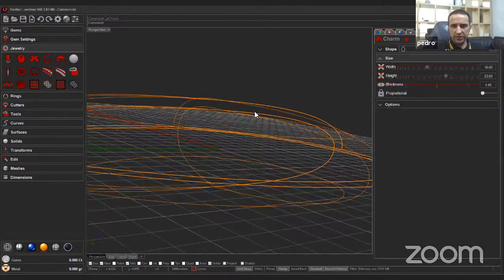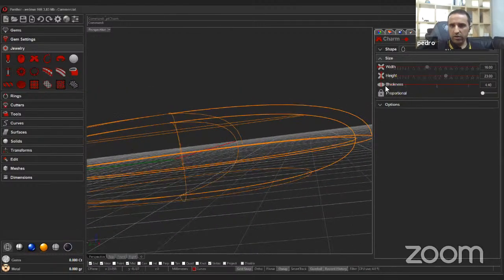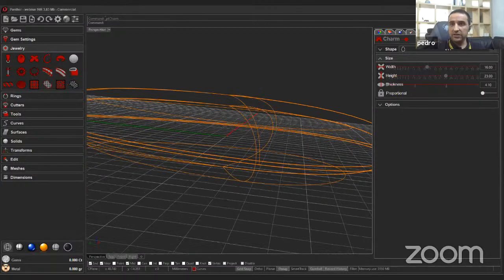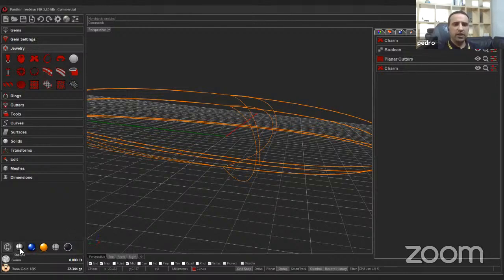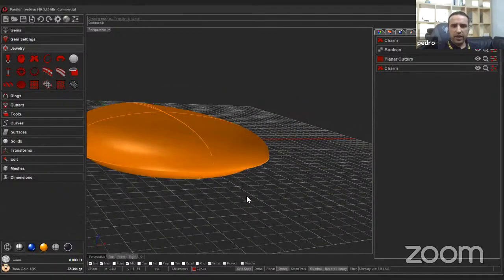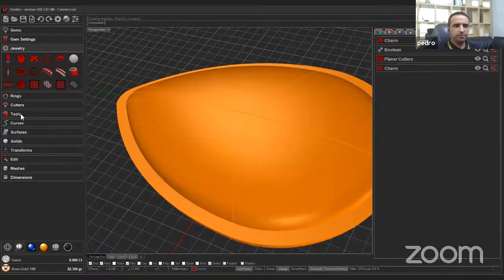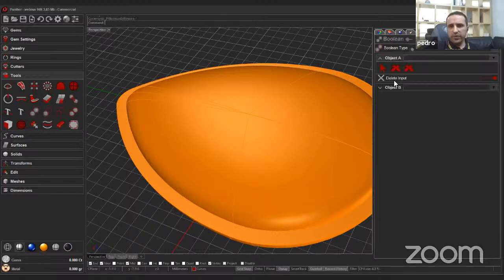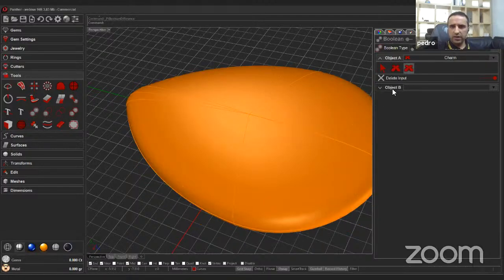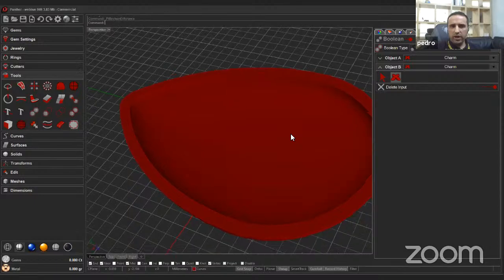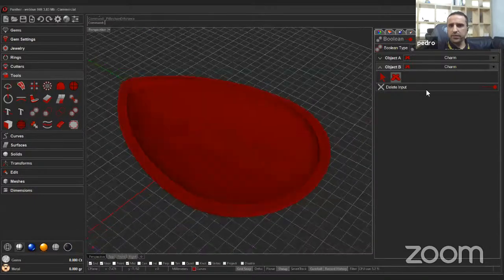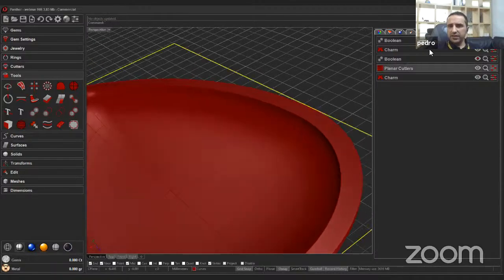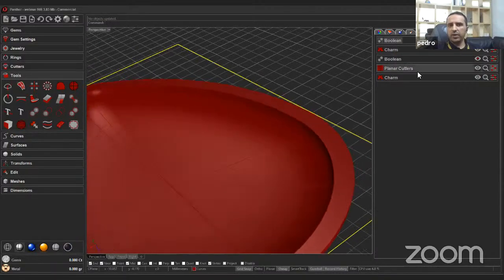You can see here I'm setting 1 millimeter for all the different walls. At this point, this is just a cutting object. So I'm going back to shade it, and what I'm going to do in here is the Boolean difference. So I'm going to remove from the first object the inner one, and as you can see, this is the result. We hollow out this part. And in here, the advantage, as I mentioned before, is that you can come back to it any moment.